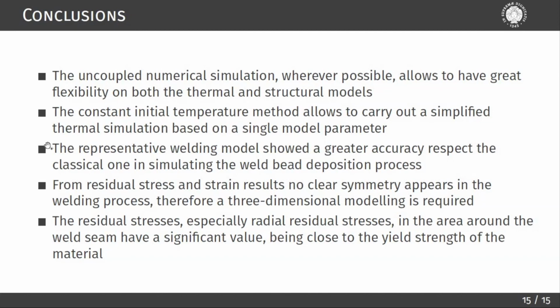In the structural part, the representative welding process showed a greater accuracy than the classic method in describing relaxed strain results. The 3D numerical model, as well as the experimental data, highlighted that there is no clear axial symmetry in strain and stress results. Finally, residual stress results showed how the stress magnitude around the weld toe is significantly close to the yield strength.